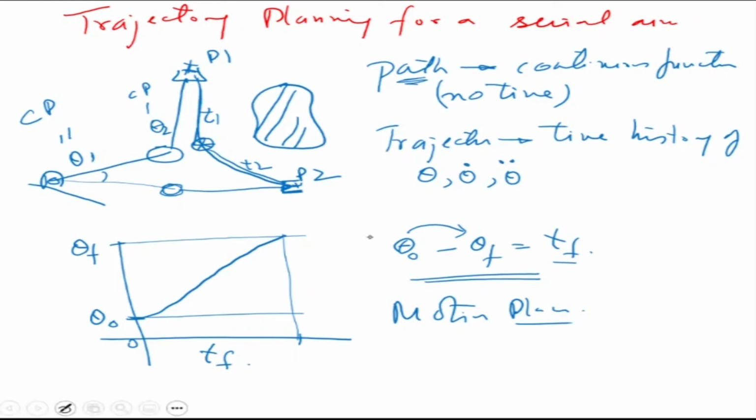Today we looked at the basic search algorithms, that is, how do we search given a network of paths. After we find the best path, then we have to go on the path. In the case of a mobile robot, the robot has to be actuated to go on the path. In the case of a manipulator, given the end effector path, you may have to find the joint trajectories by fitting a cubic polynomial. So we'll stop here and continue in the next class.